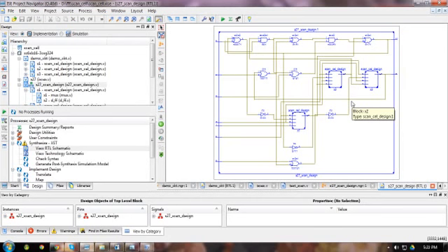And this is how you can convert any circuit from a normal circuit to a test circuit. You have to just identify where the D flip-flops are present in your design and then replace those D flip-flops with your scan cell. The main thing which you have to do is to properly make sure that when scan enable is 1, the scan cells are in cascade. They must act like shift registers, and when scan enable is 0, you must not alter the design of your circuit. And that was a short tutorial about scan cell design.